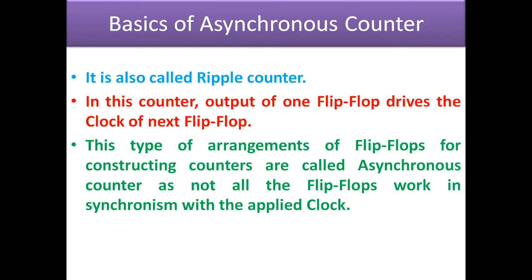In this type of arrangement, the flip-flops for constructing counters are usually called asynchronous counters, as not all the flip-flops work in synchronism with the applied clock.